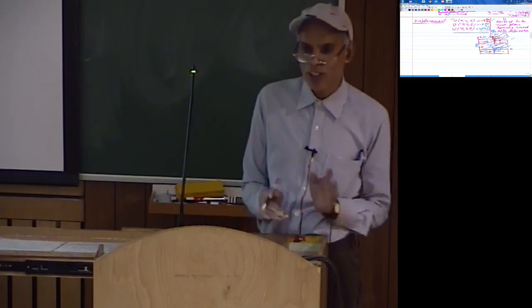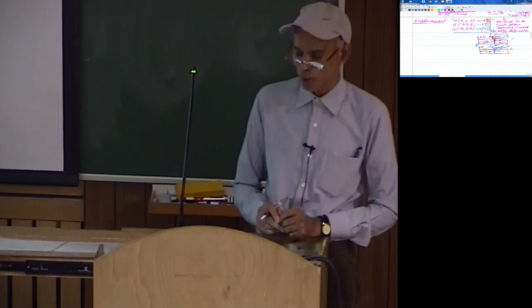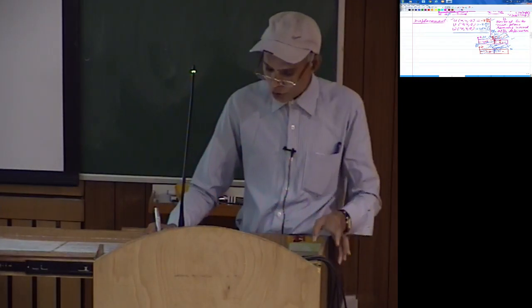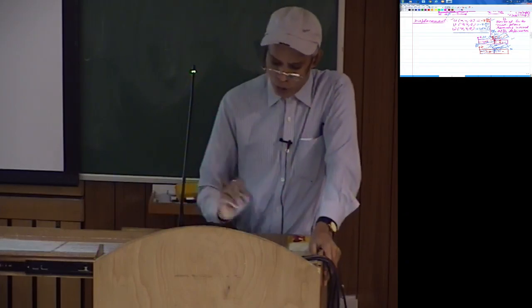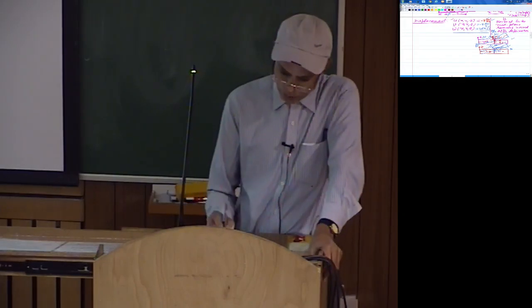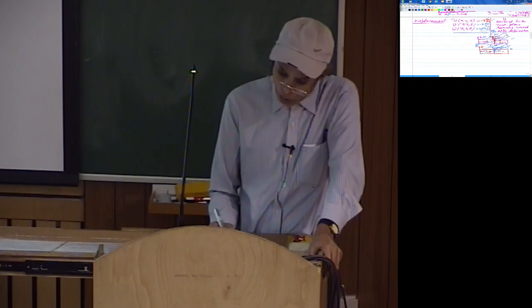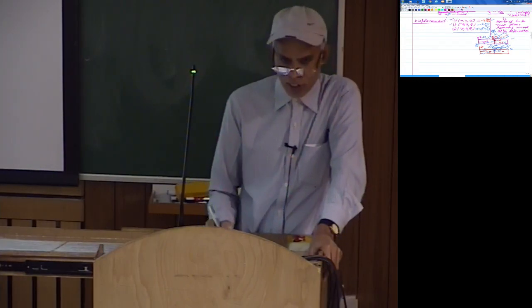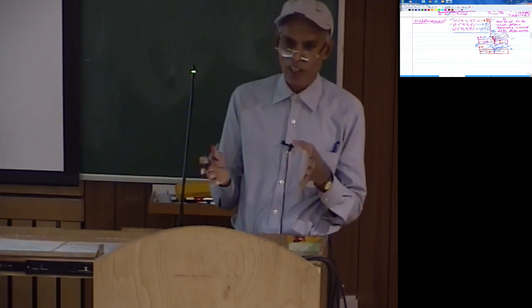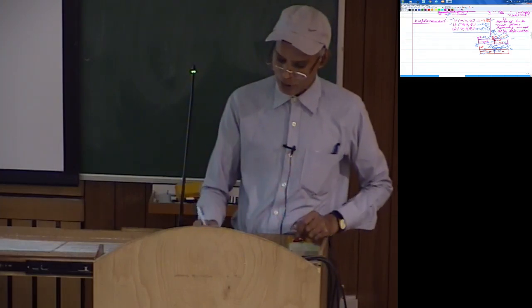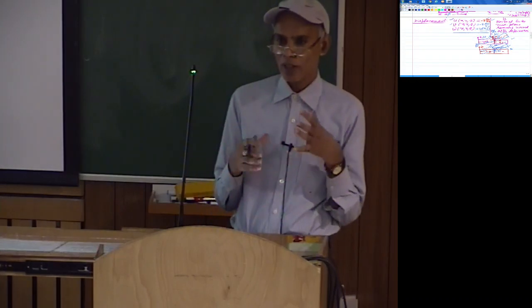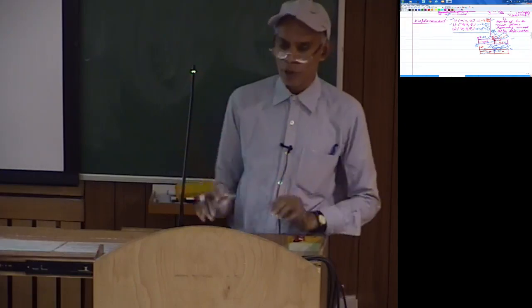Now once you have this, the rest of the steps are actually the same, but you will find there are some difficulties in ensuring the continuity of w. If we recall the Euler-Bernoulli beam formulation, since now u, v, w are the displacements in 3 directions, when we discretize a given structure into a number of elements, u, v, w must be continuous to ensure a continuous deformed structure.